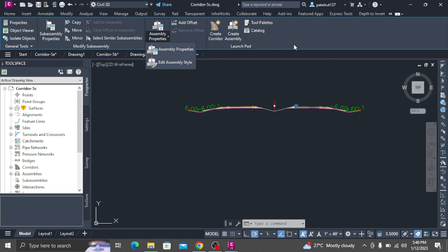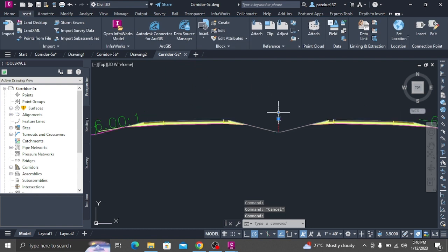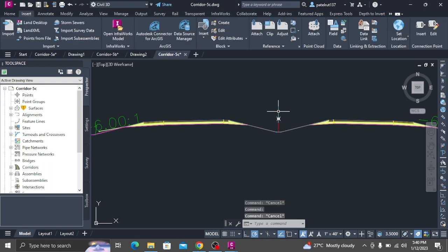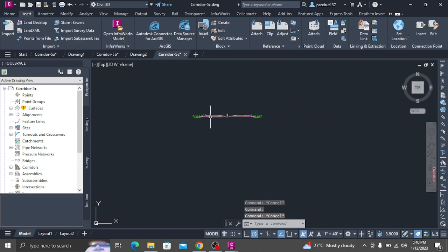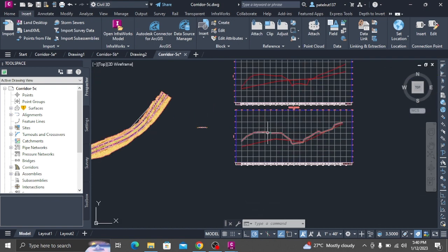Click OK. Hide and render corridor surfaces. Click View tab, Views panel, named Views List, Corridor_3D view. The drawing is redrawn to a three-dimensional view of the corridor. In Tool Space, on the Prospector tab, expand the Surfaces collection. Right-click the Corridor 1, Median Surface. Click Surface Properties. In the Surface Properties dialog box, on the Information tab, change the surface style to Hide Surface.